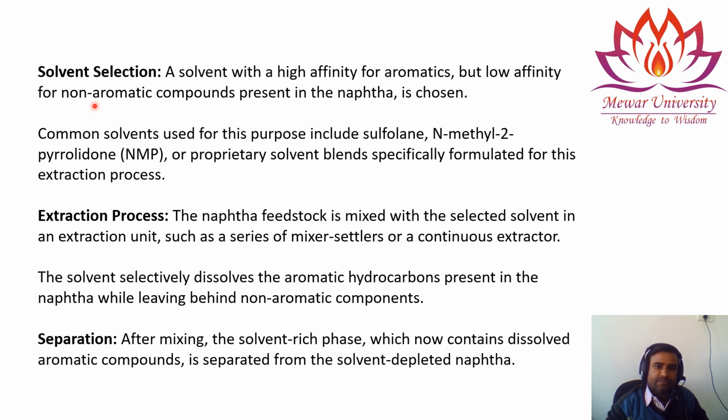A series of mixer settlers or continuous extractors will be used. It will mix the solvent and the naphtha containing the aromatics. So these compounds are mixed in the extraction unit, and the solvent selectively dissolves the aromatic hydrocarbons present in the naphtha while leaving behind the non-aromatic components. So it separates the non-aromatic components and dissolves the aromatic compounds into it.